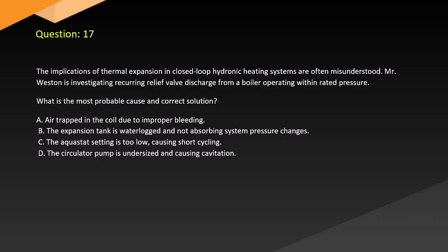A. Air trapped in the coil due to improper bleeding. B. The expansion tank is waterlogged and not absorbing system pressure changes. C. The aquastat setting is too low, causing short cycling. D. The circulator pump is undersized and causing cavitation.